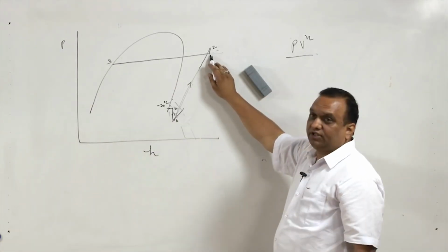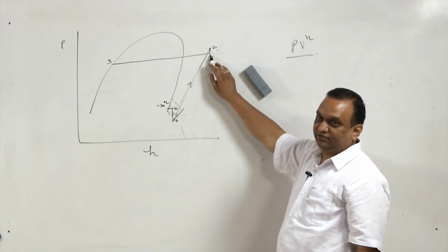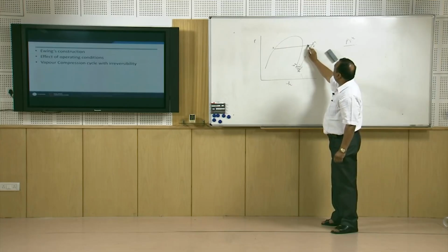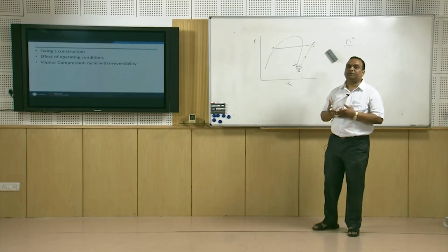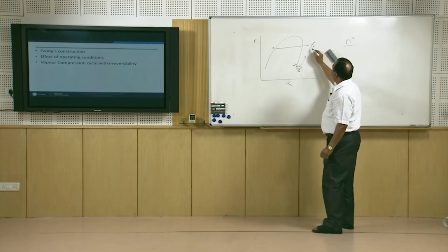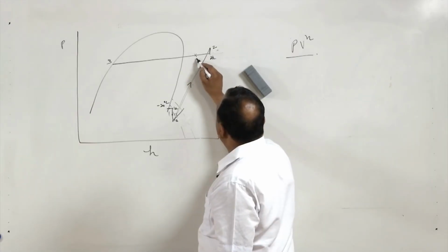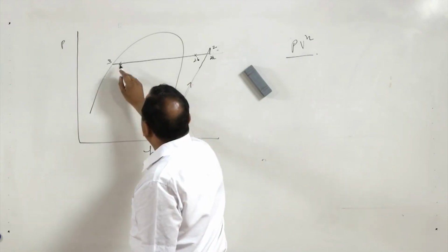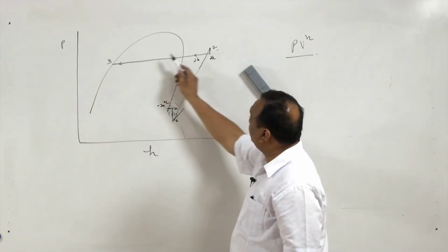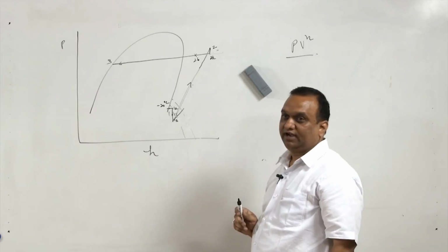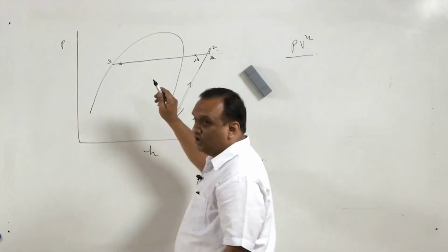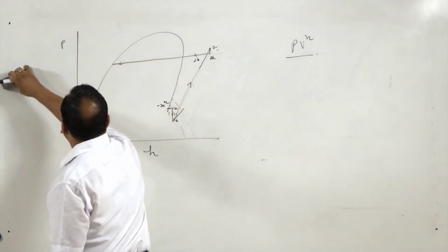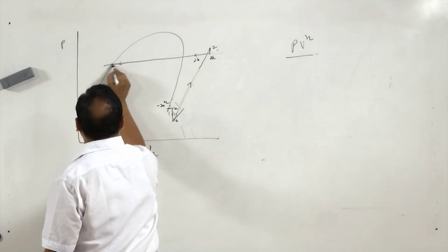Now, the vapor coming out of the compressor is at high temperature. So, when it enters the pipeline, some amount of cooling takes place inside the pipeline itself because the vapor is at a higher temperature. After this we get 2A and 2B. From 2B to 3 the condensation takes place and during this process also there is a pressure drop. Normally we do not get saturated vapor at the exit of the condenser, normally it is subcooled. So, we will go up to the subcooling state, this is 3.